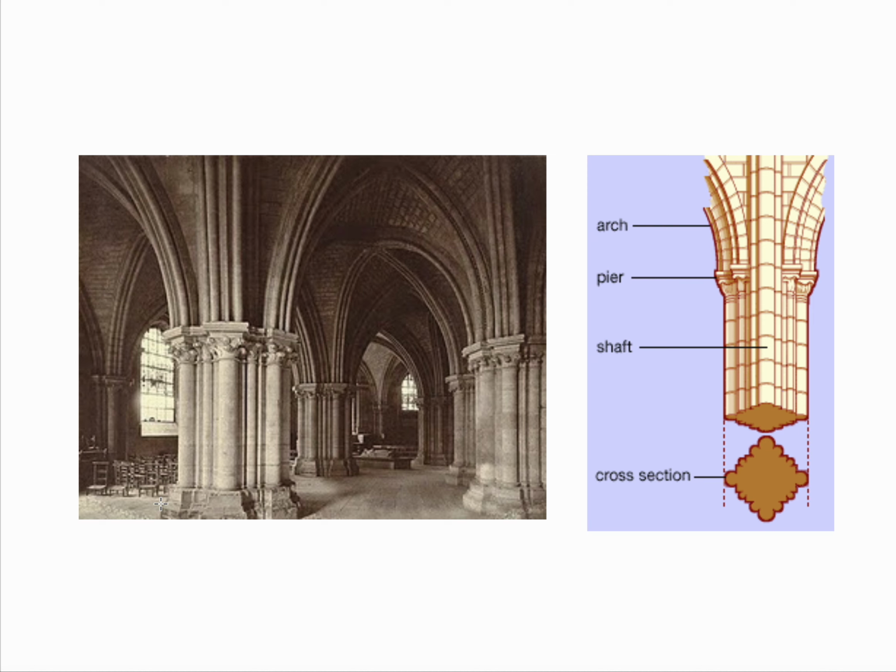Biaxial symmetry in columns is something that we've understood for a very long time. I want you to think about, say, Gothic columns. And when we look at them, we know that the forces are coming down from those arches, and those forces are then being gathered by columns, and those columns take them down to the ground. And we also know that these buildings are very much dictated by the symmetry and the geometry of what's happening up above. But just in the abstract, what if we just cut off the column and took a look at it? Look at its cross section. It's solid because it's made of stone, but look how it's biaxially symmetrical. Look at how actually then there's no weak axis to it.